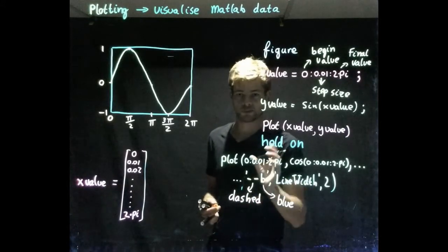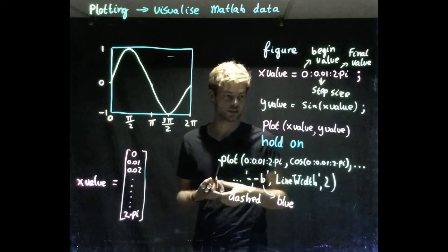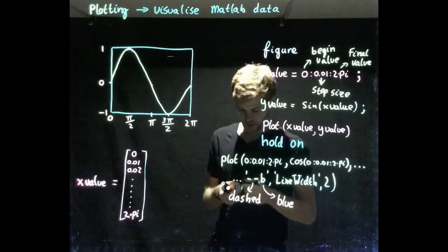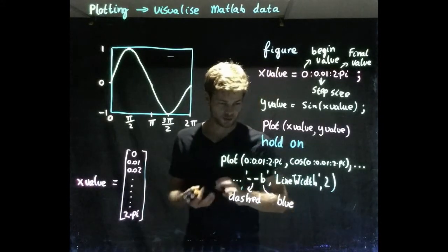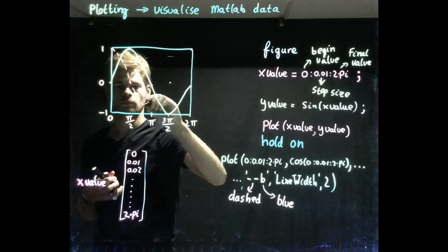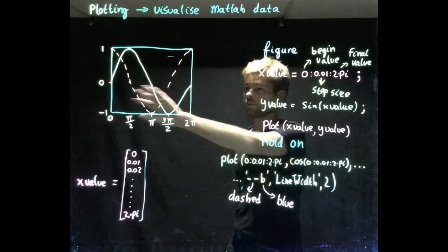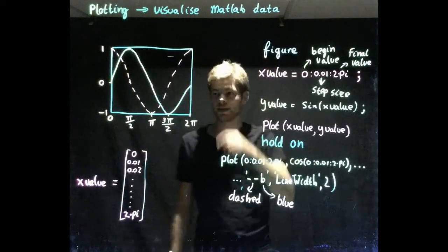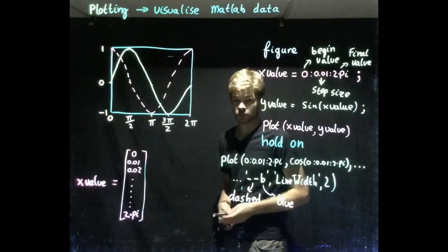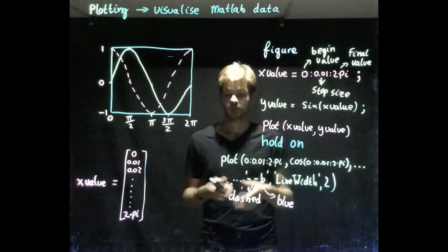Well, I have some line width. I think in MATLAB it's even thinner than this, but for now, it doesn't matter. So I'm going to plot my cosine wave now. So now you can see my cosine wave, and it is actually dashed, like I said. So that's what MATLAB will do using these commands, and there are many variations. So you should just search in the MATLAB help, and you'll find a lot more.